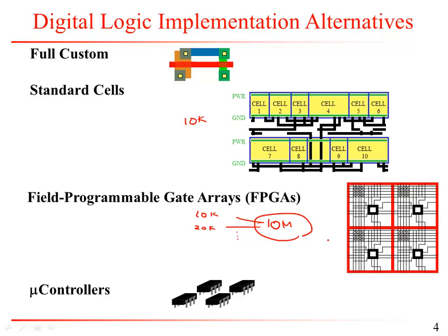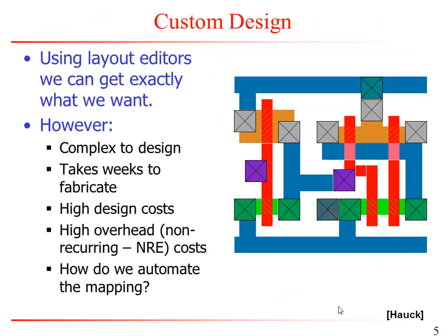And of course, I mean, you have microcontrollers and you have microprocessors. These run based on instruction sets, and in that regard, they're programmable. But in terms of performance, they're not necessarily as good as FPGAs. If in your design you need 10 multiplications, you can instantiate 10 multipliers on your FPGA and run all of them in parallel. But if in your microcontroller you only have one or two multipliers, then you basically have to serialize these operations and basically map to whatever features the microcontroller has.